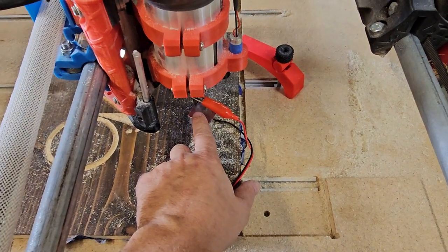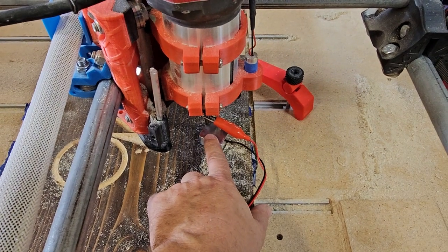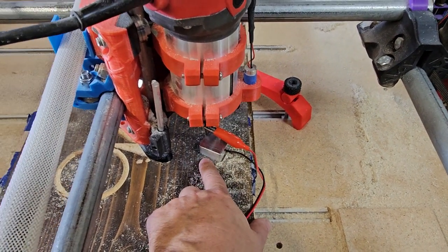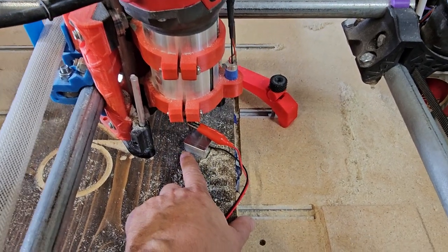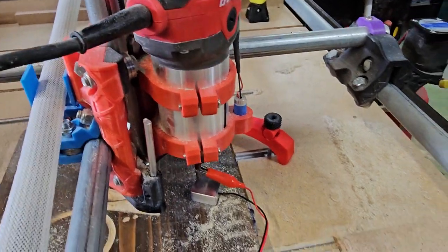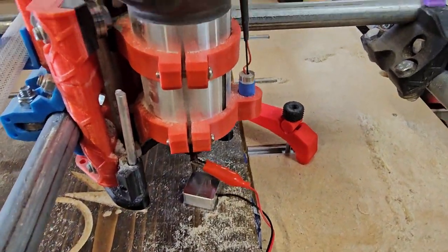And it also knows by software that this block is 15 millimeters thick. So it's going to actually set the 0 to that height minus 15 millimeters, and now we are at the board. When it's all done with that, it's going to then raise up 1 millimeter so that there's enough room for the tool to move and be able to pull the block out.